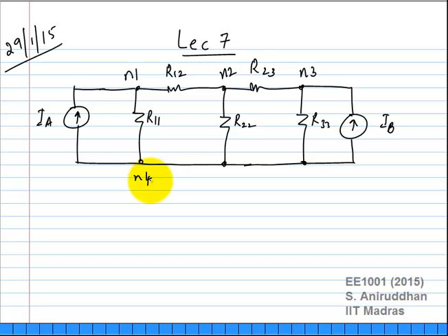What we are studying here is nodal analysis, where you write down the KCL equations at every node, okay? But the variables that we have chosen will be the voltage of every node, okay? We will use the KCL, okay? And as we saw yesterday, to solve these equations you need to use all of them, and some of them were implicit. So let us quickly write down the equation in matrix form.